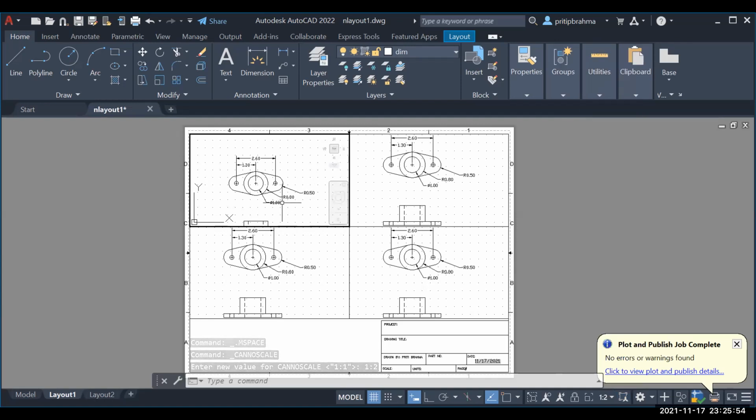So on your drawings, if you did 1/12, and then you come to viewport and you do 1/2, what's your overall scale? I'm sorry, if you draw 1/12 of the true size, and then you come to viewports and you scale it down 1 to 2, what's your overall size? 1 to 24. 1 to 24. Thank you. Yes. So you need to put that in your title block. Okay, that's your overall size now, right? But if we drew 1 to 1, then whatever the scale is in our layout is what our scale is, correct?